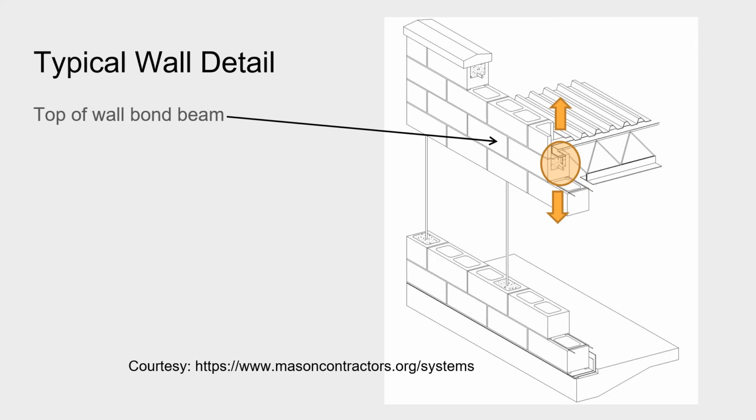The anchorage for the uplift load path must be continuous with the vertical reinforcement. A third function is to laterally brace the top of the wall. Finally, it can be the diaphragm chord if properly detailed to transmit both tension and compression. This multi-use of the bond beam is structural efficiency. While the bond beam appears simple, all of the bond beam features must be fully detailed for the mason to construct the walls.